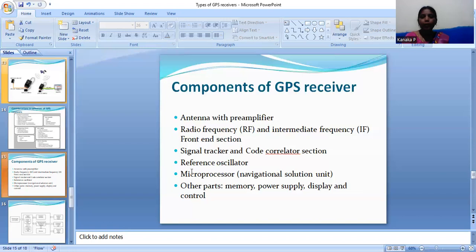C is the velocity of light in the medium through which it travels. D is the distance between the instrument and the target. So that is called the pulse method. Next one is the phase difference method.